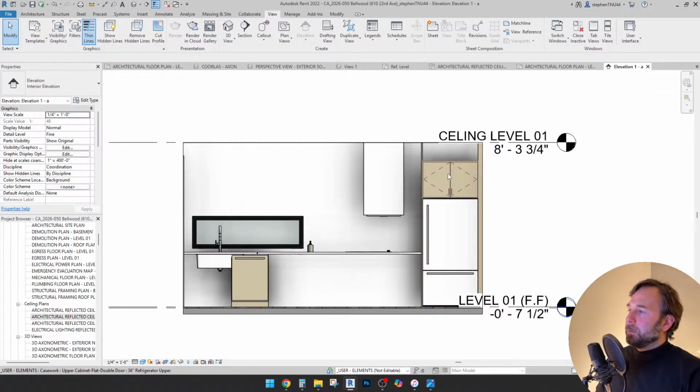And this is where we have to make the decision about cabinets going full height up to 9 feet or building out a soffit. And for this scheme, I actually wanted to build a soffit out all the way across at that 30-inch depth. So the only cabinet that would be 30 inches or 24 inches that's set forward on the uppers would be this refrigerator cabinet.